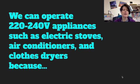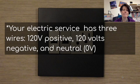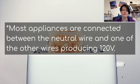But we can operate 220 volt to 240 volt appliances such as electric stoves, air conditioners, and clothes dryers because your electric service has three wires: 120 volts positive, 120 volts negative, and neutral, which is 0 volts.